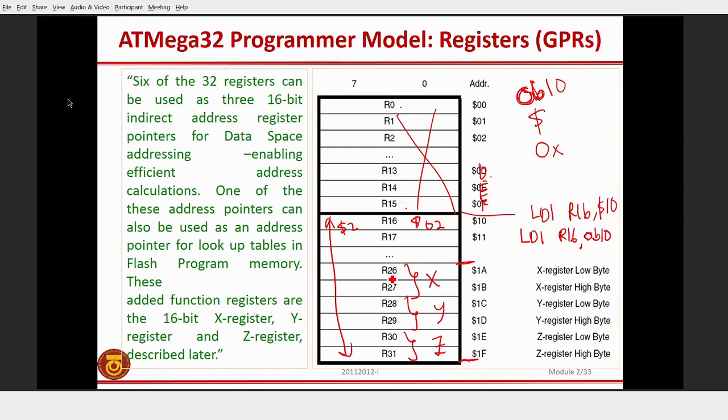So the address needs to occupy more than 8 bits. If you calculate that, you need 4 hexadecimal digits, which is 16 bits, because it's a 16-bit address. So you need 4 hexadecimal digits. So this one will occupy 2 and 2. For example, let me write 0310.